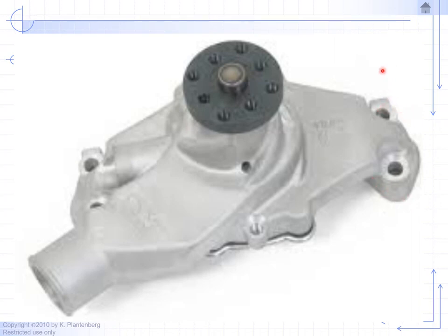That'll guarantee that the bolt will go in perpendicular. When you bolt it onto the engine block, you don't want this surface to be at a different angle, causing stress on the head of the bolt and causing a twist which may snap the head off of the bolt. So here we want parallelism between the counterbored holes and the base, and it'll be mounted onto the front of an engine block. Okay, next slide.